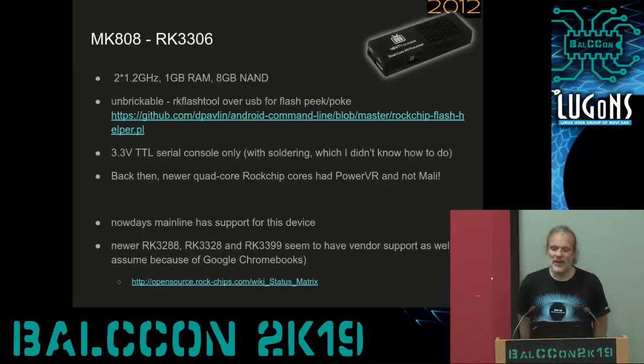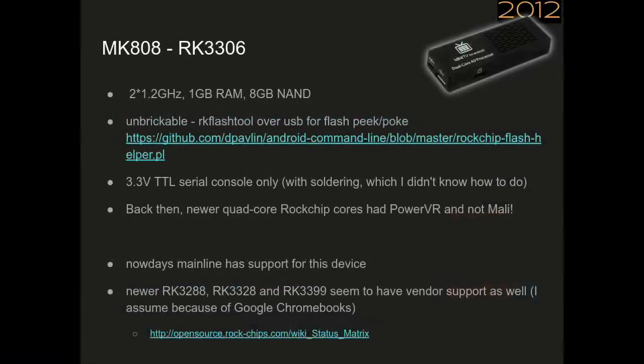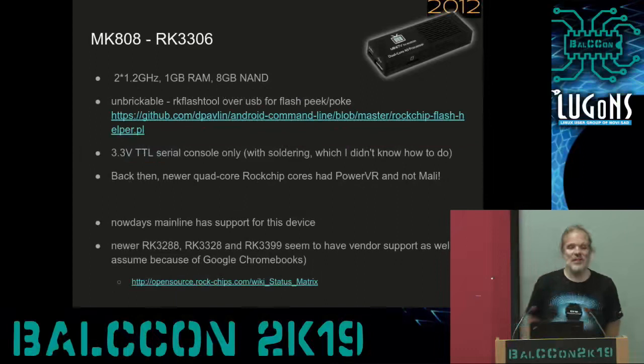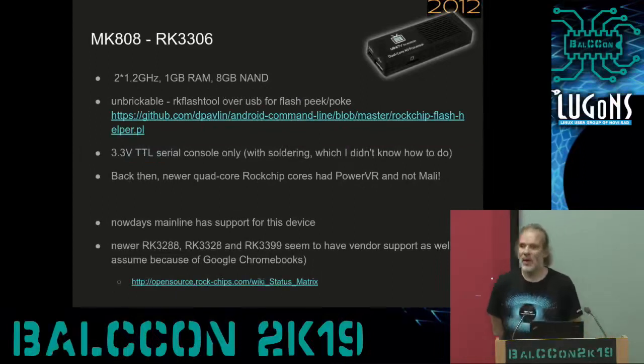And that device was my first attempt to actually run my own kernel. At that point, it was not supported at all. There was not even a vendor kernel which I could compile and make somehow usable. But I learned that Rockchip, and we'll see that's mostly true for all the other manufacturers also, does have support which enables you to reflash the device using USB only.